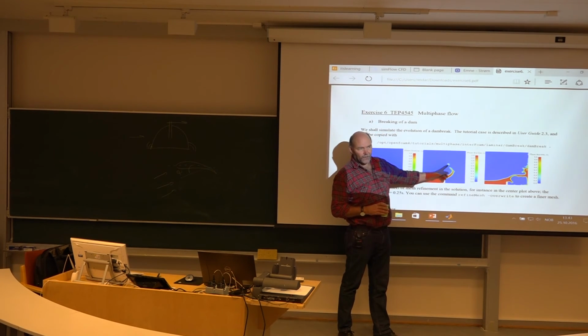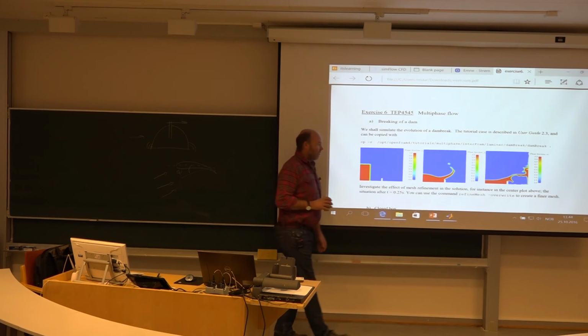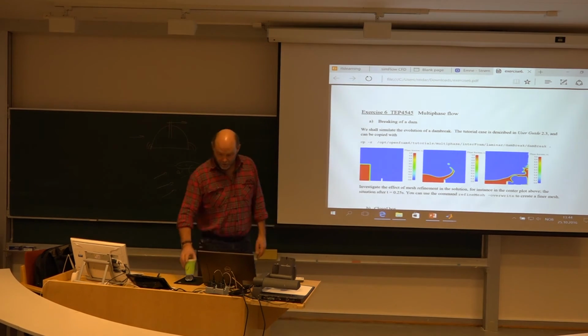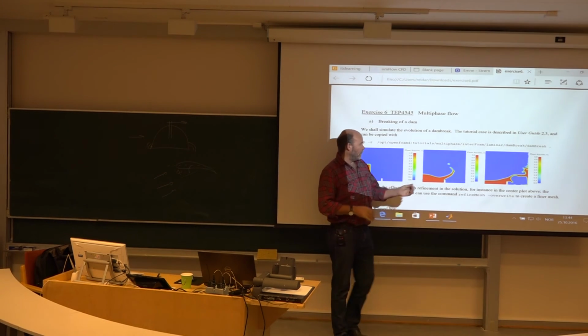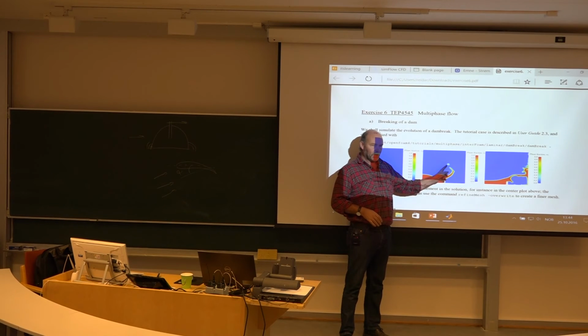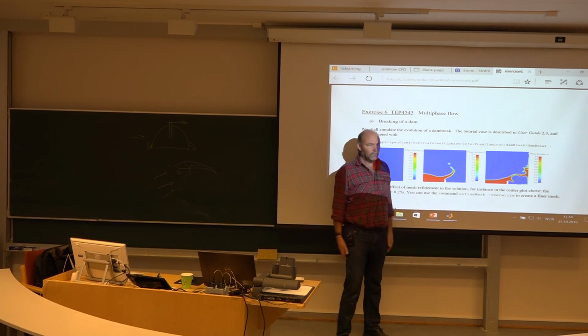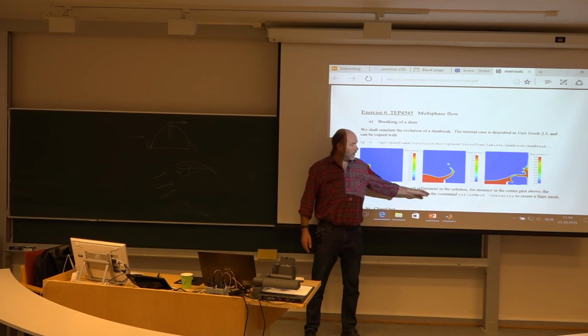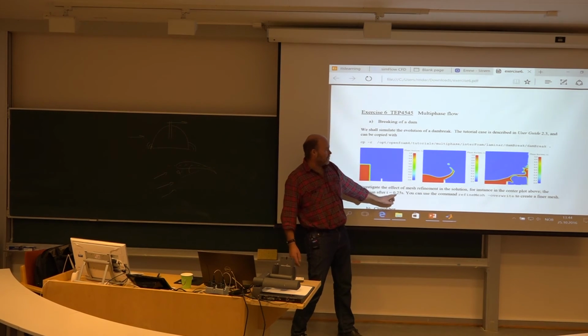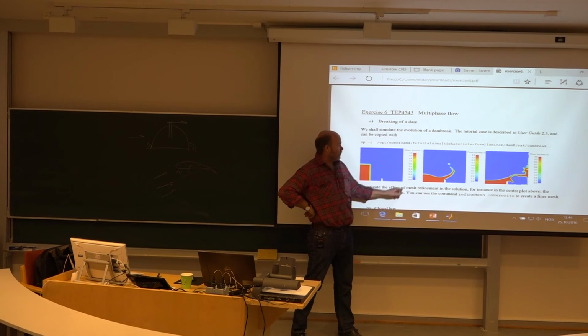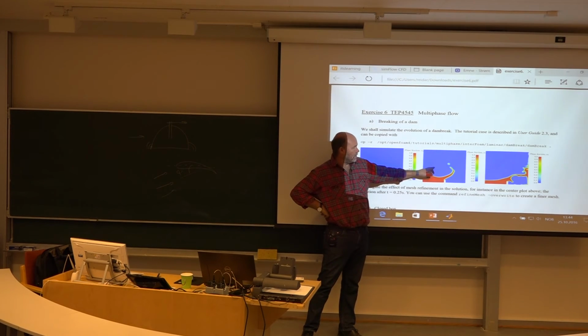And also then if you look at, say, this image and focus on this little droplet that is here, how will it change when you change the mesh? Is this correct? Should it be one droplet or maybe several? I don't know. So you use that one as a sort of predictor, something that we should validate or verify, that yes, it's supposed to be like this or should not be like this. Play around with it, finer and finer mesh. Also, it's only after 0.25 seconds, so you don't have to simulate for so long to get this image.